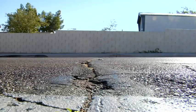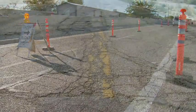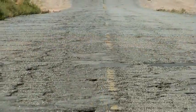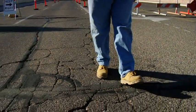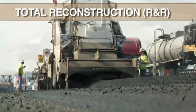Many of our roads are under-designed for today's traffic loadings. These structurally deficient roads are no longer suitable for roadway maintenance techniques, such as chip seals, slurry seals, and thin overlays, and require total reconstruction. There are two paths an engineer can take to address this problem. One option is a total reconstruction of the road section.